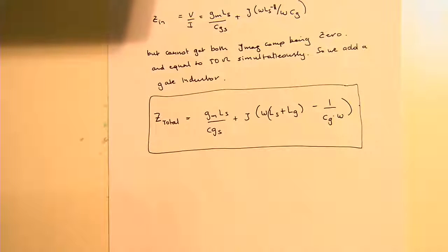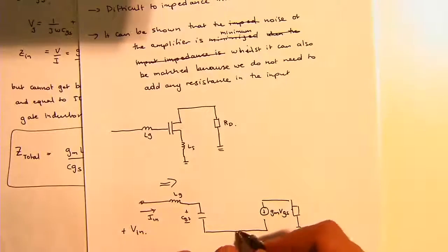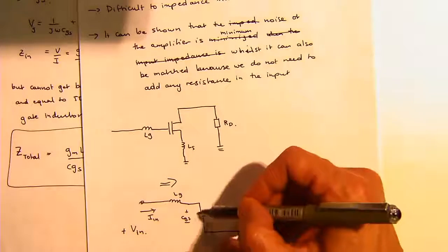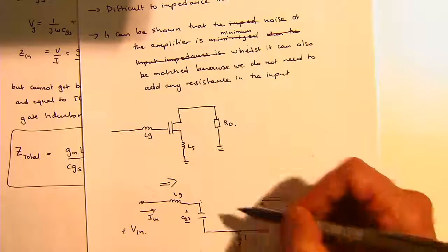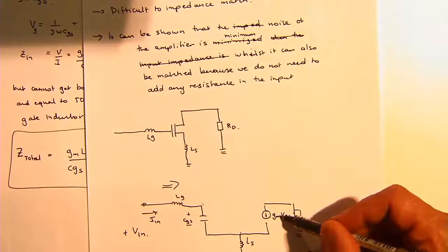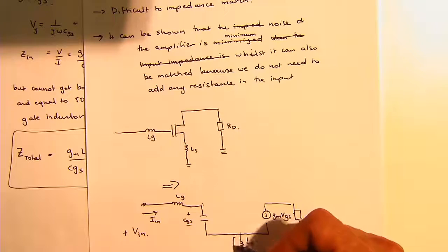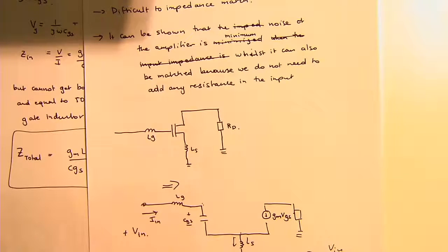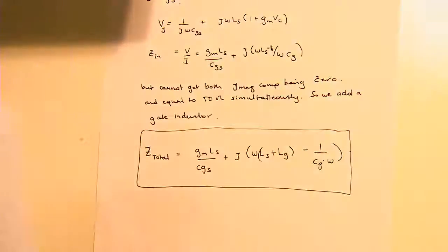All right, so for everyone's benefit, I've said this voltage is V, and then if I work out what VGS is, I can work out what gm is. If I sum the currents here, you can actually work it out. Because this is a current source, none of the current that you're putting in through I in can go elsewhere, all of it has to be sunk through here. So the current here is going to be I in plus gm VGS. That's another hint to help you work out the input impedance, or the transfer function characteristic.